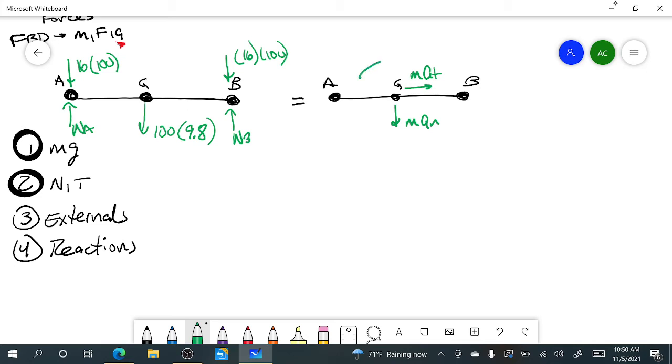Last but not least, I want to make sure that this object isn't rotating, so this is going to represent I_G times alpha, the rotation of the actual body. That's to say if maybe B is rotating a little bit more than A, that's going to create a general plane motion effect. But generally speaking, you want to have three: an x, a y, and a z. In this case, our x and y are going to be rotation variables, tangential and normal, because I know that G is orbiting some fictitious radius of curvature because of the two bars holding it on its sides. They're holding it still, so I have a feeling that my alpha is going to be 0. But this value, I'm sure I'm going to be able to solve for it.